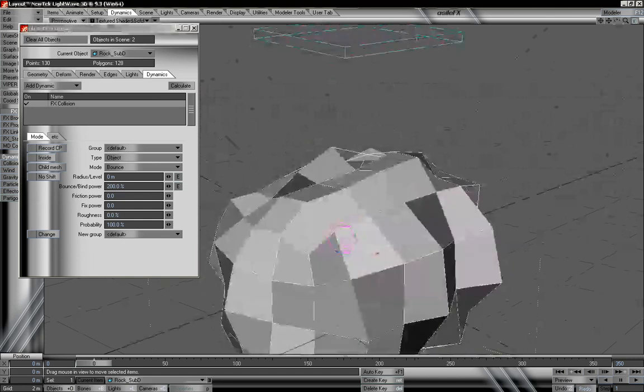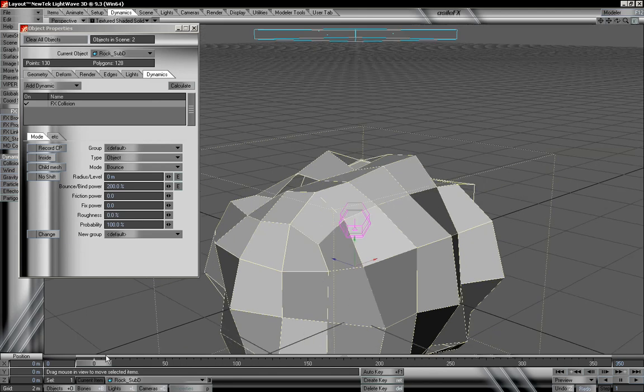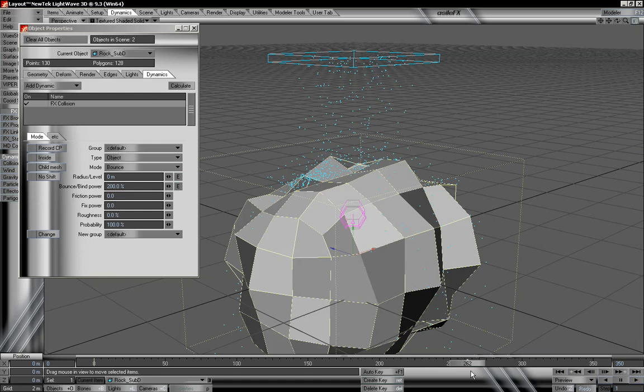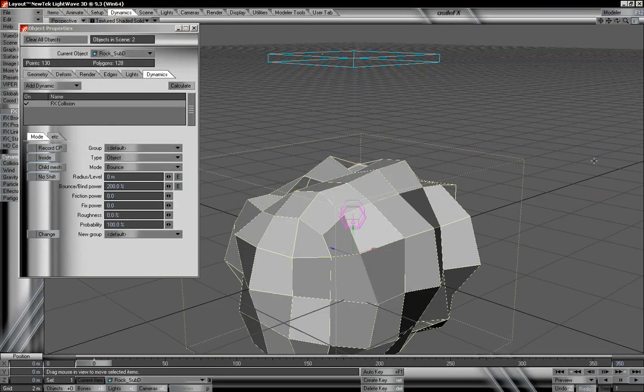And now if you notice, I have a lot of non-planar polygons that are showing up within our scene. And we can see the different areas where they are disappearing because they are non-planar. But that does not seem to affect our collision at all. And our particles are still not going through our object. So it's very nice that we don't have to worry about non-planars affecting this collision, and we don't have to worry about those gaps that we see as a display error affecting the calculation of our collision.